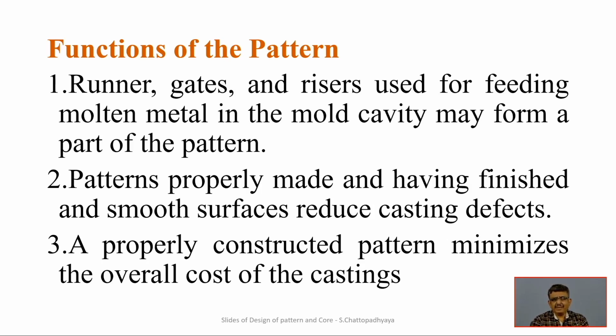A pattern properly made, with finished and smooth surfaces, reduces casting defects, because the casting will be produced as per the pattern. If the pattern's surfaces are not smooth, we cannot expect very good smooth surfaces on the casting. So the pattern has to be made with appropriate surface finish to produce a quality casting.